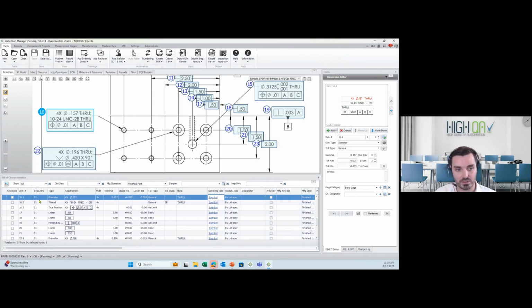My system, as you can see, is set up to balloon it as one single balloon, 16, and then down below 16.1, 0.2, and 0.3. If you wanted these to be 3 separate balloons, 16, 17, 18, you can. Also, if you wanted to explode the multipliers out, over here to the right, I click this multiply dimensions button.